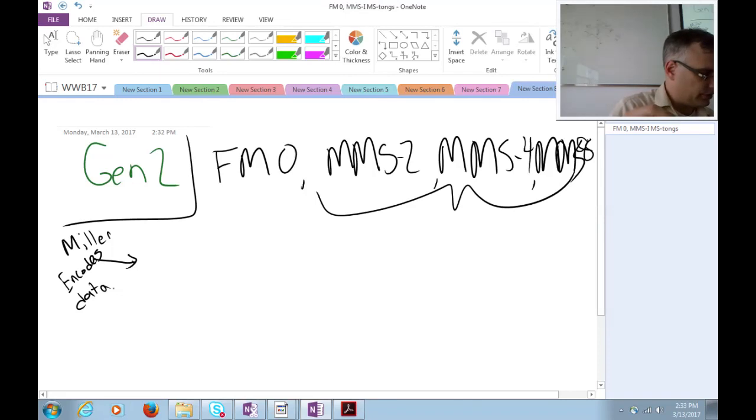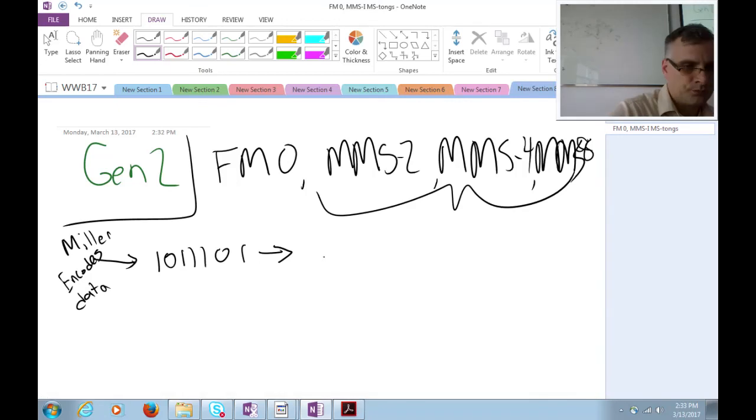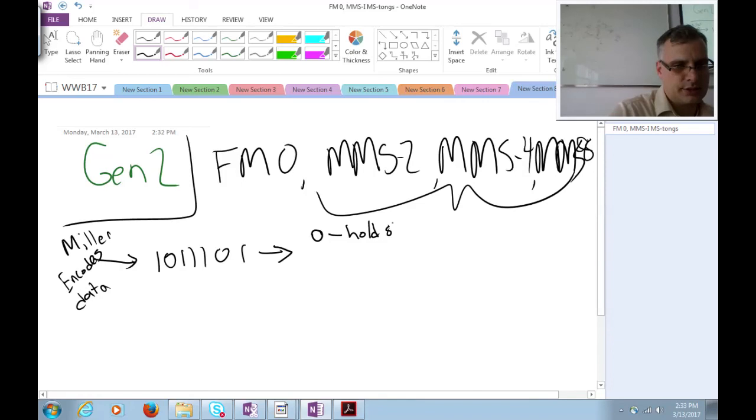Okay, so what does Miller modulation mean? What does it mean to Miller encode? So first you take a series of 1s and 0s, and then if it's a 0, you hold the state.